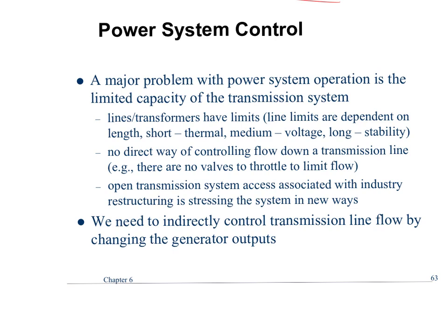Now, does generation drop out? Do they drop out and the frequency starts to drop? Yes. Well, actually, it's not generation. So the question is, what happens on bad frequency condition? Usually it's under frequency. There are actual automatic systems that the transmission owners have, like Amera, Avangrid, Eversource. All those companies actually have UFLS, under frequency load shedding schemes, that are automatic. They take over within a certain period of time. If the frequency is below value, bye-bye this substation. It's going to be de-energized.